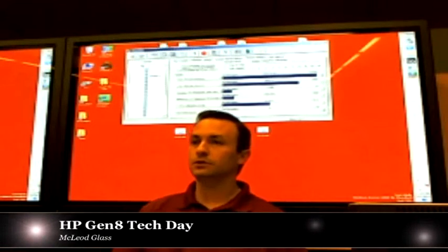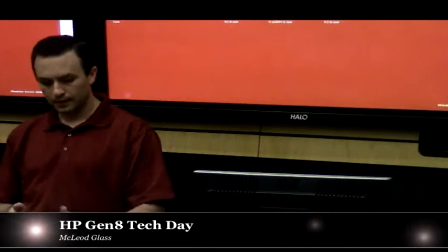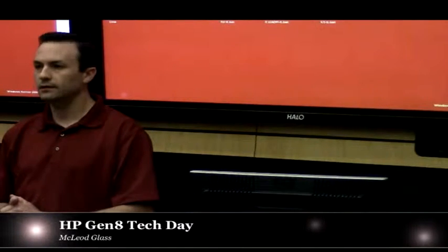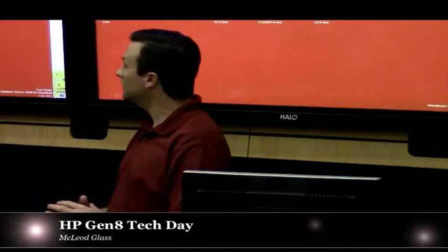With this generation of controllers, we've made the processor faster. We've got additional cores inside of it. We've optimized our firmware for the I/O path to the RAID controller itself. And as you can see demonstrated, the fruits of our efforts, we're hitting 206,000 IOPS off a single smart array controller. Now on the back end, I've got 8 solid state drives that are delivering these IOPS. And the workload that I'm running here is just a 4K random read workload.